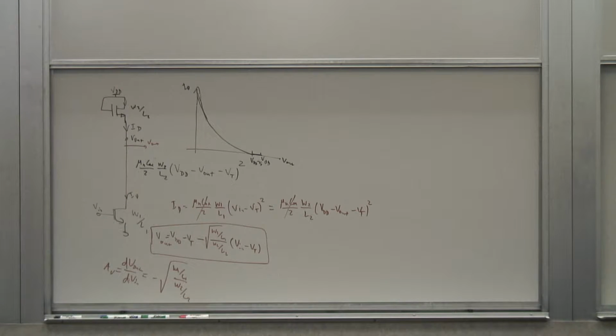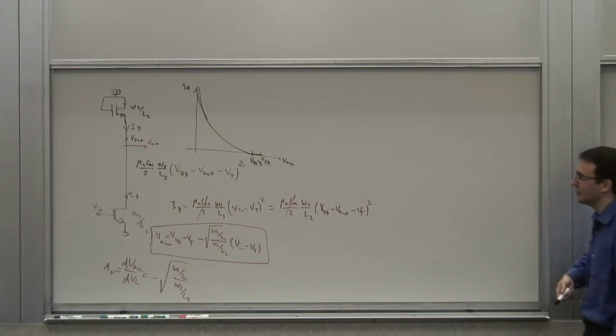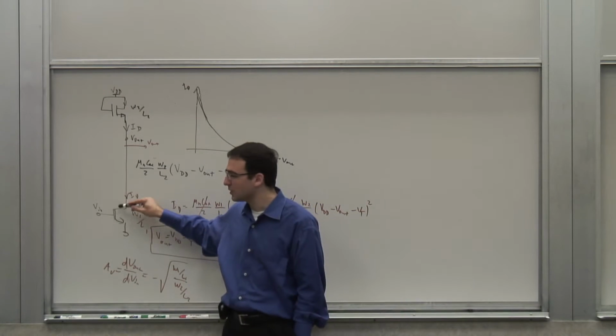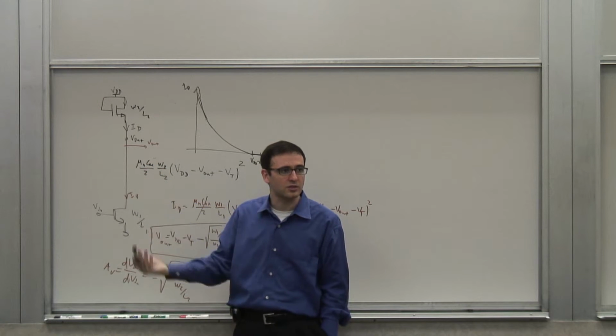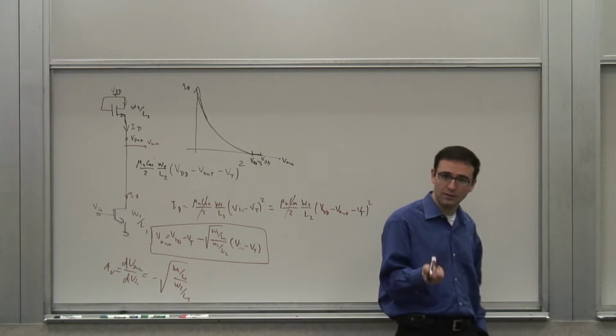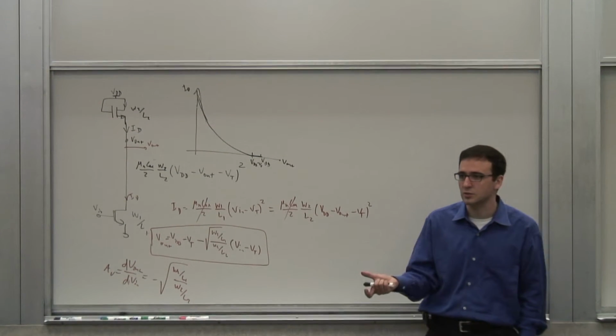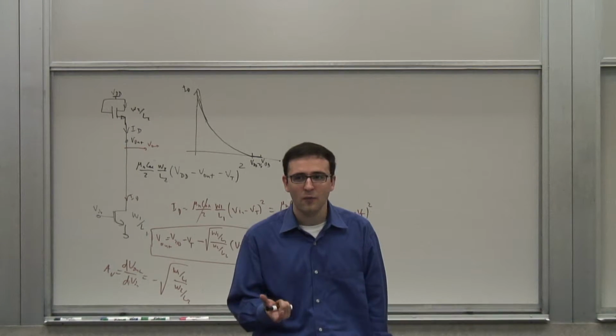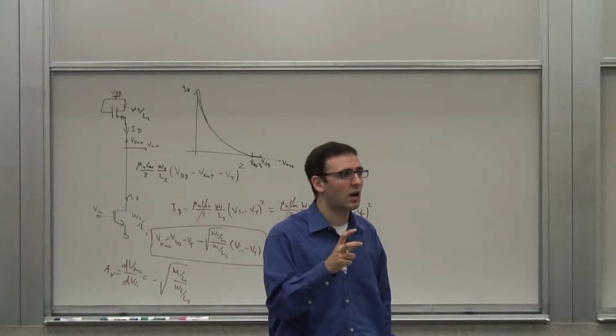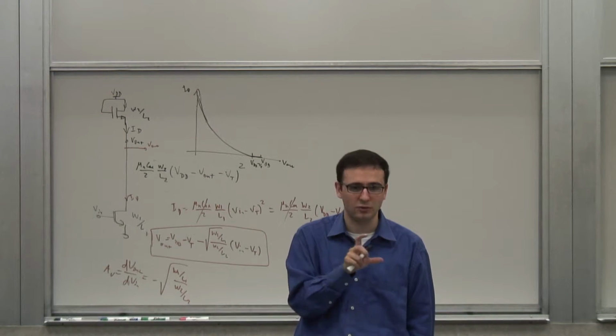Now, it's a good thing because if you want to amplify a signal faithfully, copy it faithfully, then you have to be able to have a linear amplifier, or emulate a linear amplifier as much as you can. Because if you have nonlinearity, you amplify the basic signal, but once your signal becomes large enough, then you will have harmonic content and there will be harmonic distortion. So for instance, if you want to make high quality audio amplifiers, one of the very important parameters is the total harmonic distortion, or THD, in an amplifier, which basically tells me what is the energy in the harmonic content compared to the energy of the fundamental, which is the part that you're interested in.